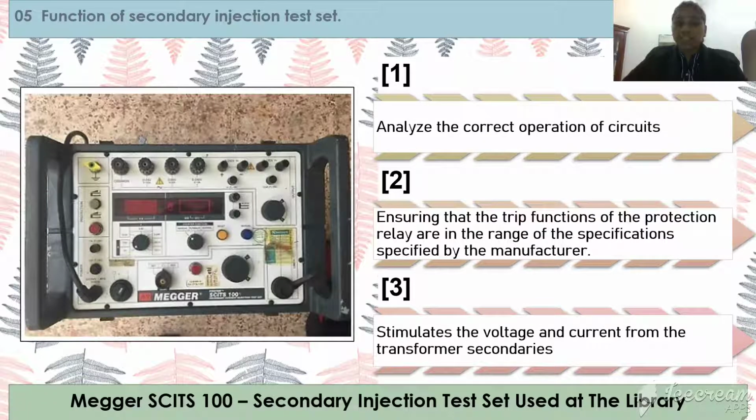This test also simulates the voltage and current from the transformer secondaries by applying either single phase or three phase voltage and currents into relays, performing all the important testing with faulty and normal conditions.